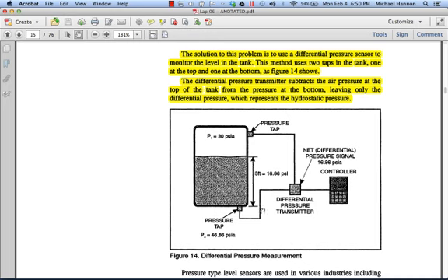This is a good example of the accumulators in the containment building, where we have a concentrated borated water volume, and then we have 650 pounds of pressure above it, and this is actually nitrogen gas. We maintain that pressure for emergency situations, for example in a LOCA situation.